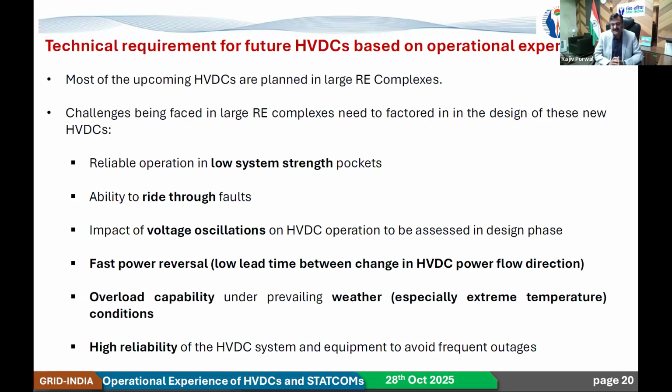But for these HVDC systems, there is a lot of debate about LCC versus VSC based HVDC. If we go for LCC, definitely at times there would be quite low system strength. So how they will behave during those times will become important. Those reliability considerations have to be there for the future design. They should be able to operate successfully in low system strength, ride through faults, and handle voltage oscillations.